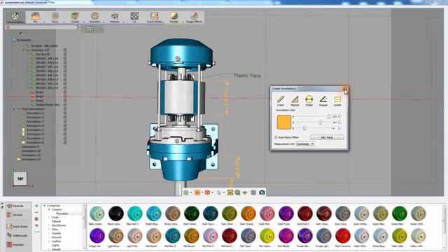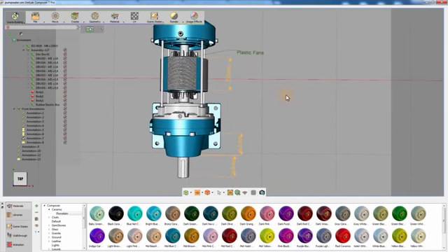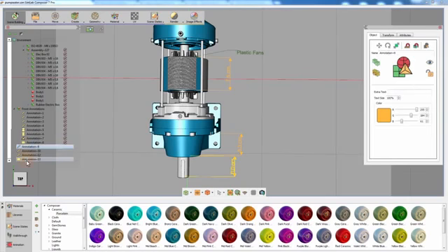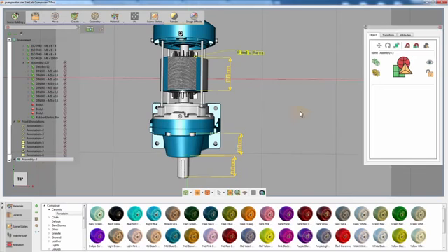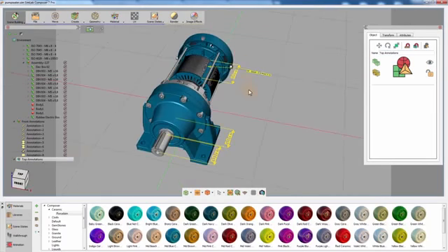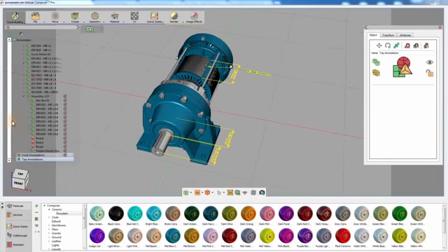Once you are done with creating annotations in the top view, select the recently created annotations and right-click in the object tree and select Add Parent. Then rename the parent group to Top Annotations. Now that all the annotations in the scene are grouped according to their corresponding view, you can hide and show them as needed.